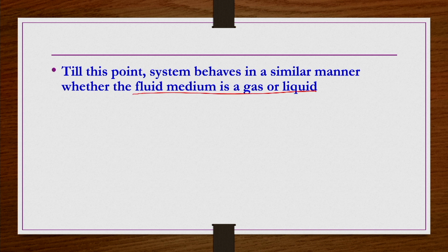So, till this point the system behaves in a similar manner whether the fluid medium is gas or liquid. As I mentioned already, depending on the fluid medium that is being used to flow through this packed structure, whether it is a liquid or gas, different characteristics may be obtained at higher velocities, especially at higher velocities. But till the point where fluidization takes place, or the point at which the buoyant weight of the bed is balanced by the overall resistance offered by the particles, or the drag on all the particles, the system is going to behave in quite a similar way, whether the fluidizing medium is a gas or a liquid, it does not matter. That is, till the point where fluidization starts, or till the point where the fixed bed conditions perish, and from there the fluidization point starts, the breakthrough point.